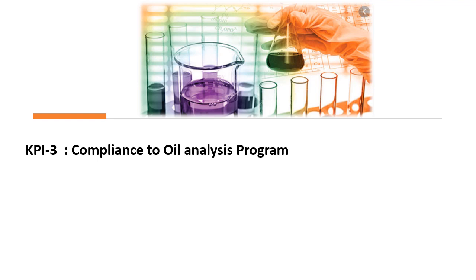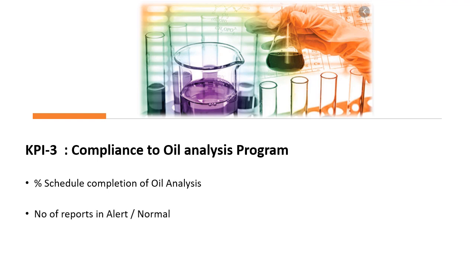The third KPI is the compliance to oil analysis program. A good lubrication program will also contain the oil condition monitoring program, also known as the oil analysis program. So we can measure the compliance to the oil analysis program directly. We might have a specific schedule for different equipments, maybe quarterly, half yearly, or monthly. The adherence to the schedule of those oil analyses can be measured, and we can also track down to